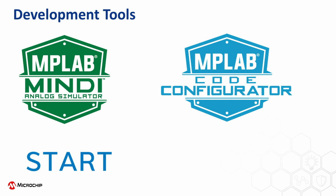After downloading and installing MINDI, you may need to add the integrated OPAMP models into the tool. This video will show these steps, however future versions of MINDI will have these models pre-installed. After simulating the integrated OPAMP circuit, I will show you how to use the graphical code generators, MPLAB code configurator, and Atmel start to create the required APIs to implement the OPAMP circuit on the device. You can find a link to these tools in the video description.